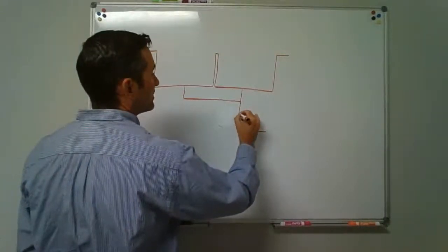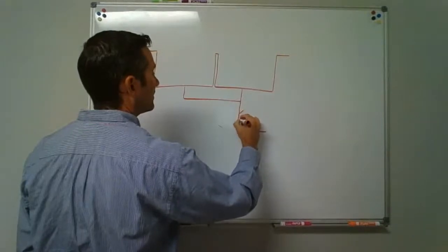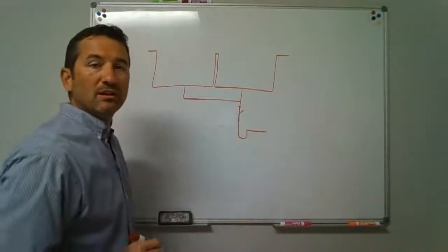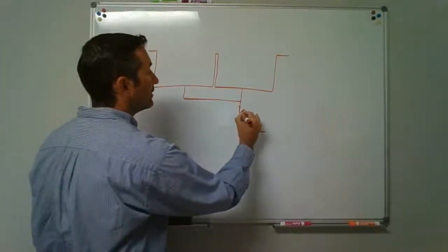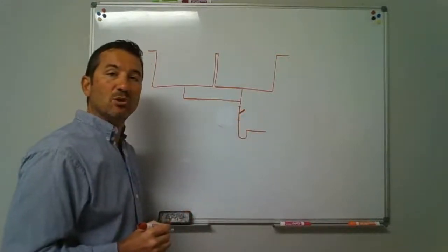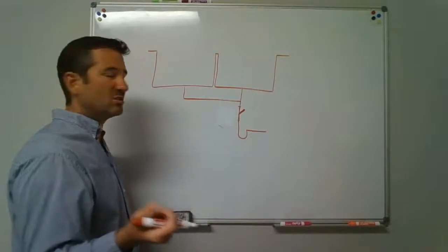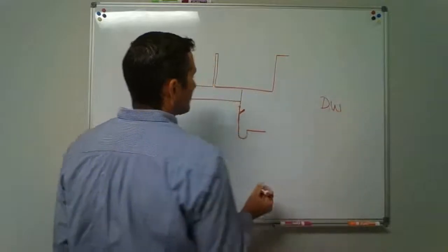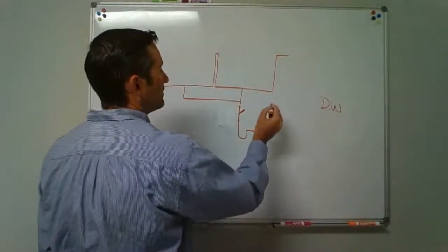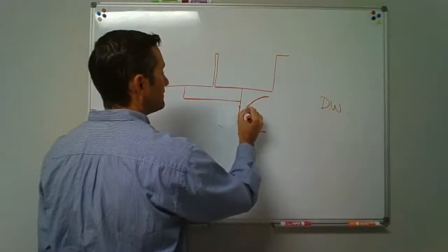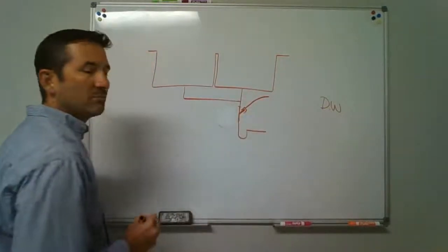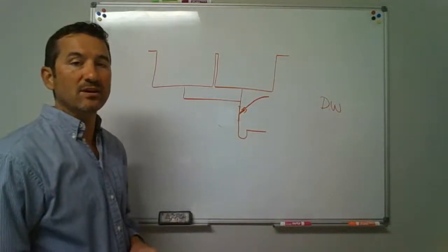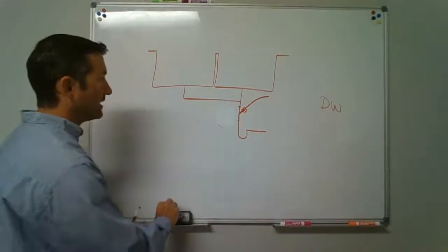So we could put in this section here what's called a dishwasher Y tailpiece, that little fitting right in that we attached. That's got a little kind of a barbed connection on the end of this right here. It comes in. It's got a flexible hose and a little rubber end to the drain hose of your dishwasher. So if you're going to put the dishwasher over here, you're going to have a flexible hose that's going to come and connect to here. Okay. A lot of them already have like a spring-loaded clamp that goes on, or you can just put a hose clamp on there, and that's another possibility as far as where it can connect to.